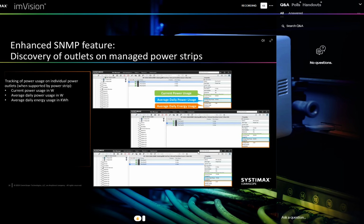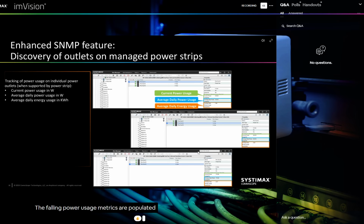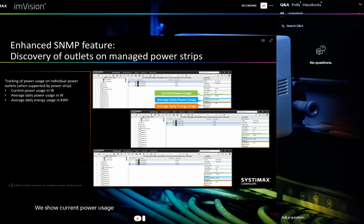When supported by managed power strips, System Manager can periodically collect and track per outlet power usage data via SNMP. The following power usage metrics are populated in dedicated fields within the properties of each individual power outlet. We show current power usage in watts, average daily power usage in watts, average daily energy consumption in kilowatt hours.